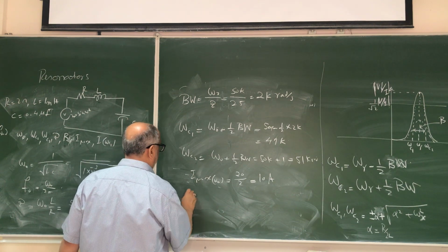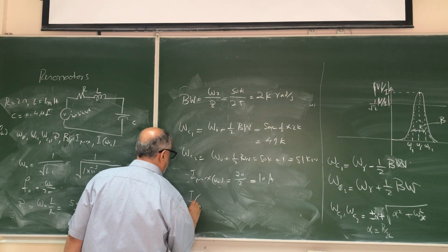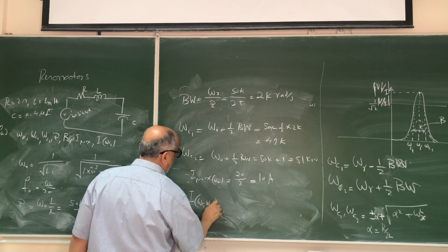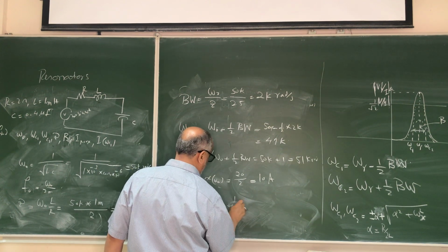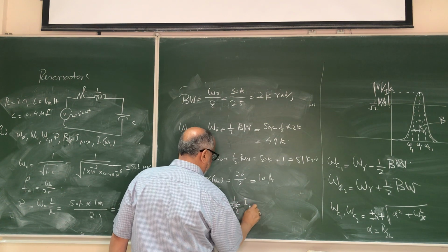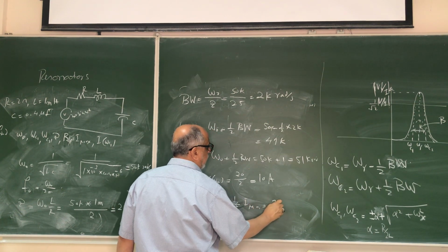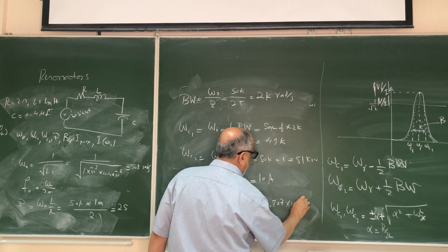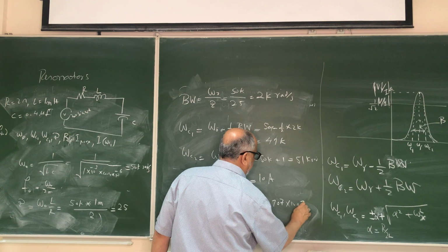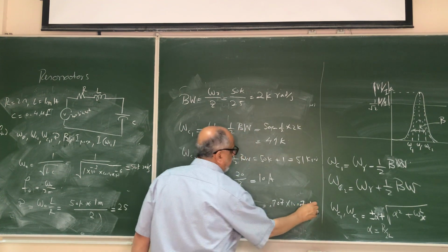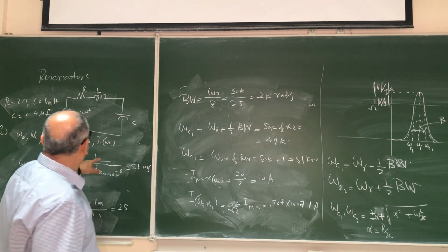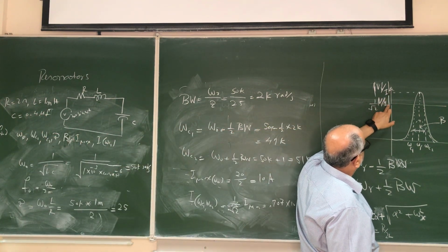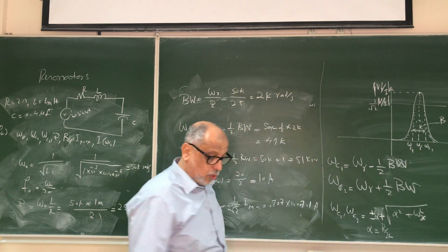I at 3 dB, or half power, at omega C1, which is the same as at omega C2, is 0.707, or 1 over root 2, of I max. So that will give me 0.707 times 10, so that will be 7.1 amps almost. So that is the current here, the maximum current is here, and the current is here, okay? Right.